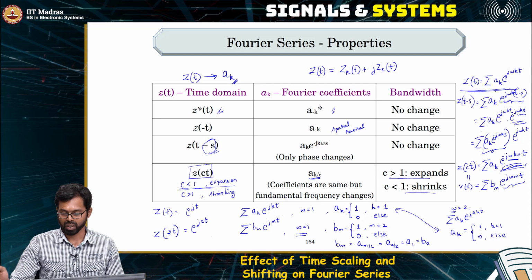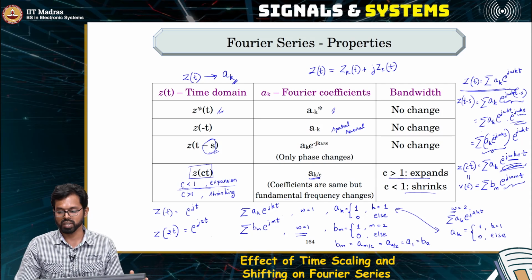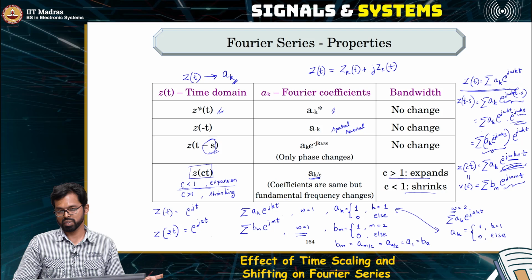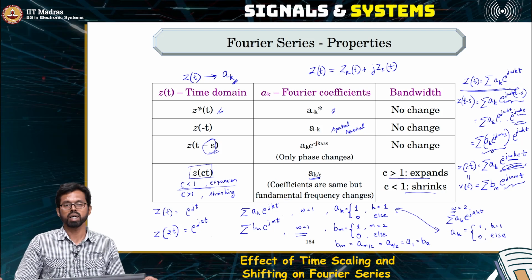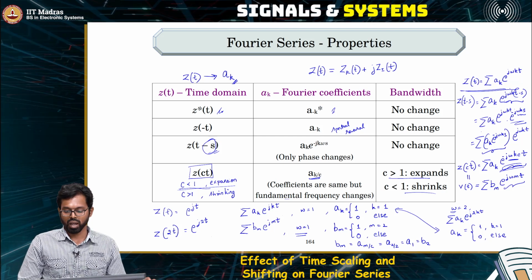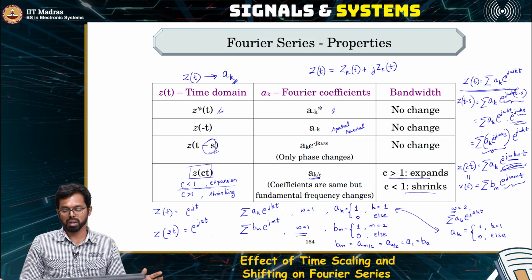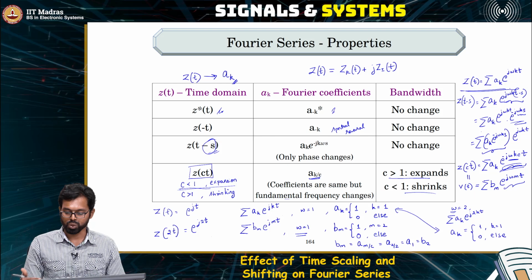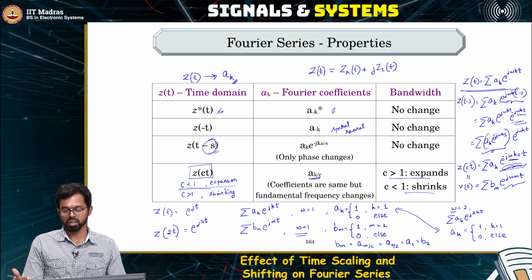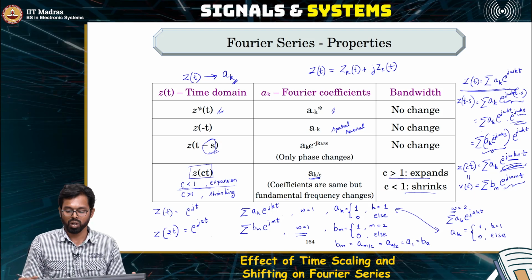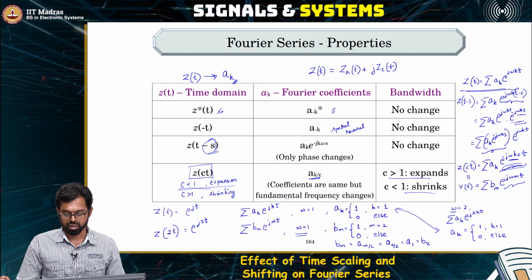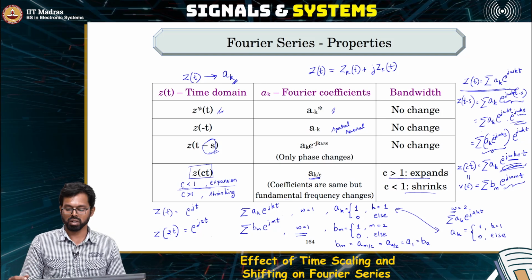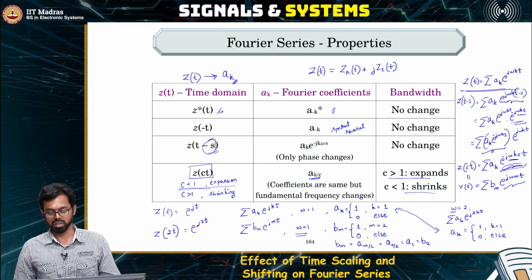That's all we need. Basically, you are decomposing everything in terms of phasors, and to describe a phasor, we need its magnitude and its frequency. That's all. And how we represent that, it's up to us. So we can have multiple representations. In this case, we saw two different Fourier series representations for the same signal by having different fundamental frequencies. So I can change the fundamental frequency and keep getting different representations.